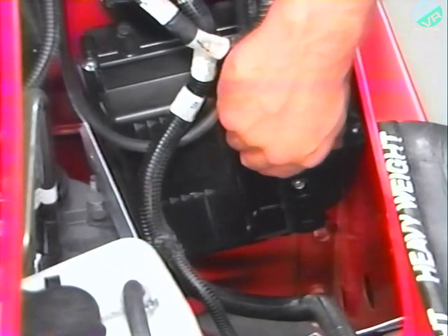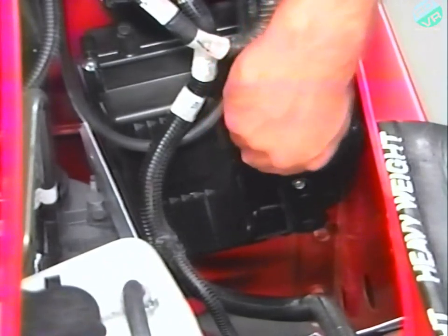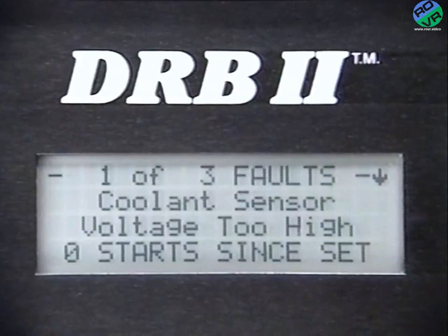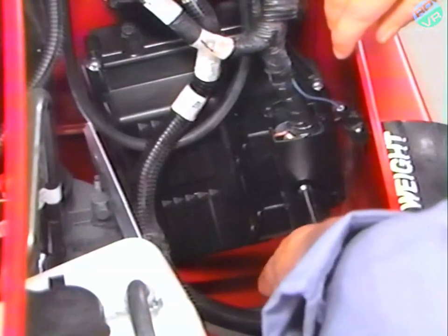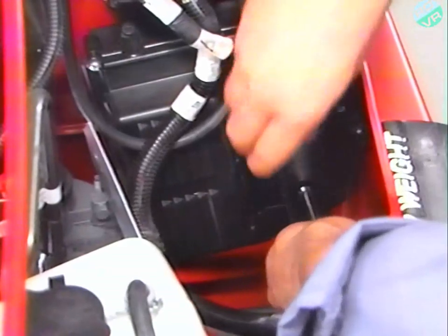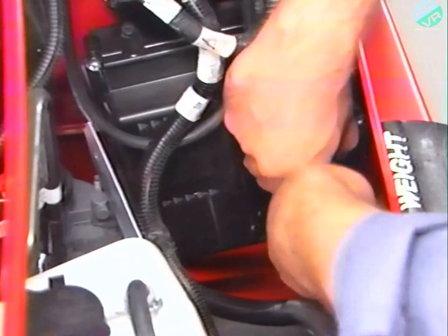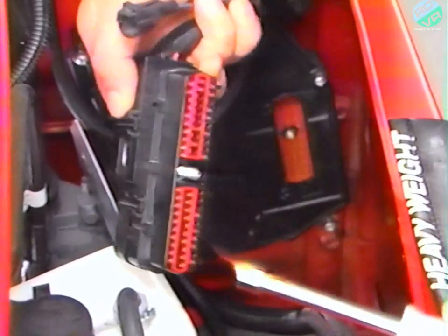One of the first steps in a thorough visual inspection is to check that the 60-way connector is fully inserted into the engine controller and that the mounting screw is tightened down. After all the fault messages have been read, it's a good idea to remove the 60-way connector and check the engine controller and the connector for damaged pins or pushed-out terminals.